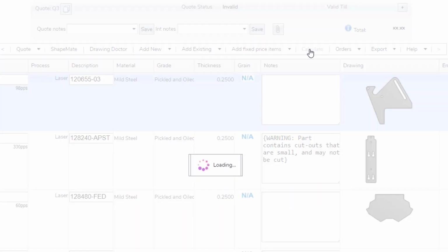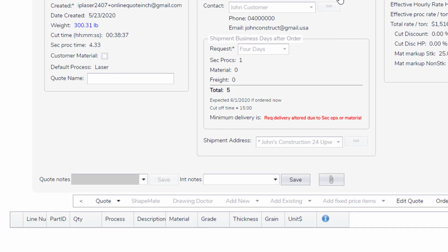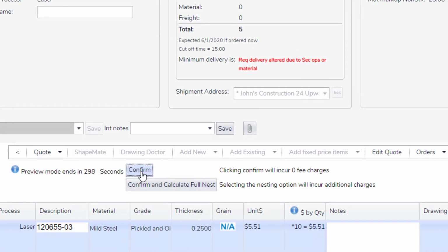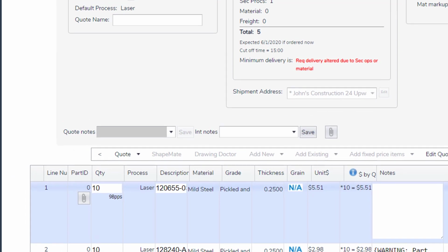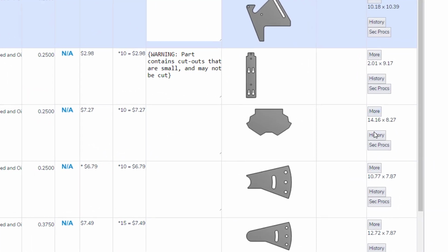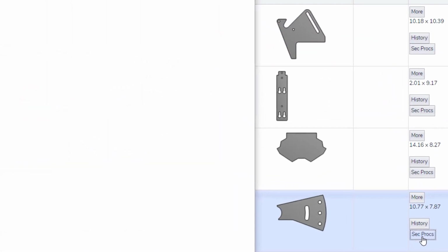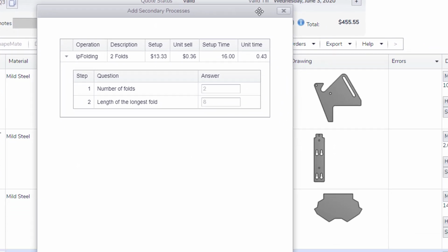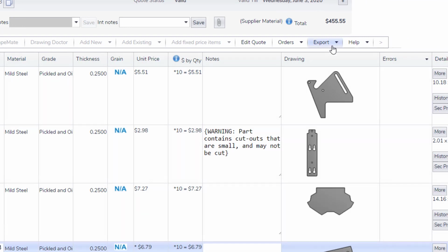Once we have interrogated the drawings and applied the material grade and thickness, we then have all the parameters of the part available, including size, mass, surface area, etc. So if, for example, you wanted to create a secondary op for powder coating, you would use the area of the part in your calculation to determine the square feet. Or perhaps tapping a thread could use different tap sizes with different costs for tap and material thickness.